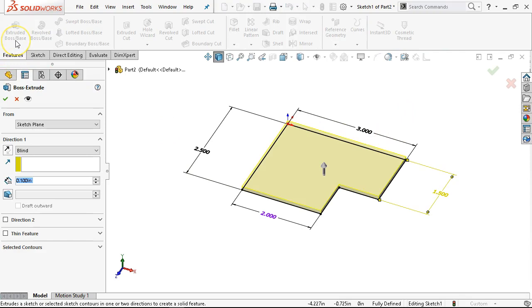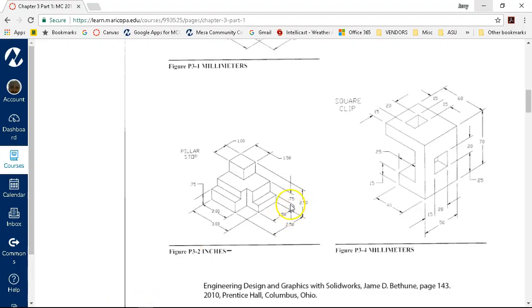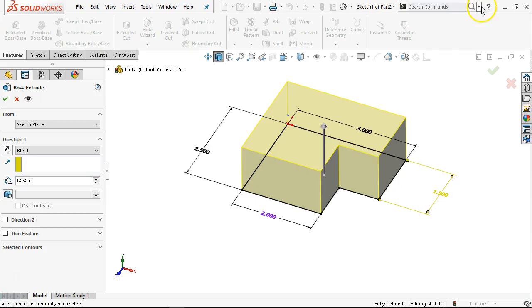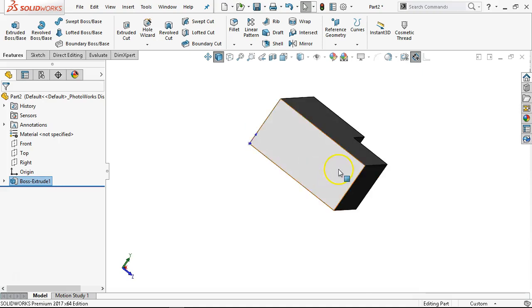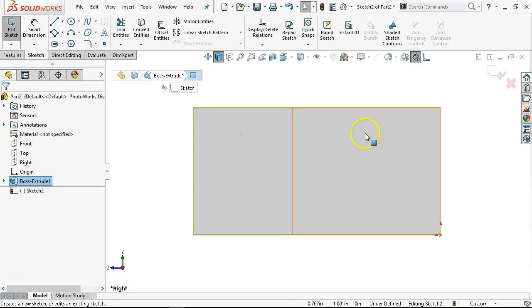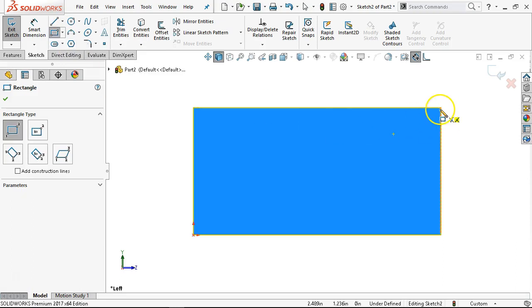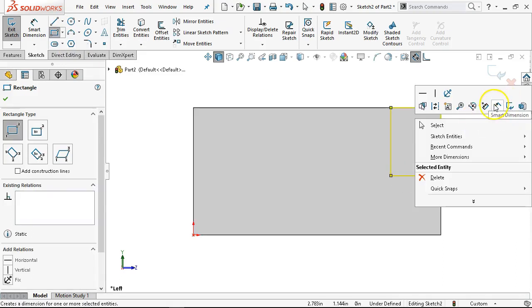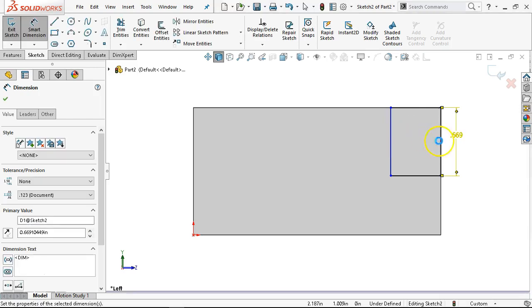We're going to extrude, and this is going to a height of 0.75. Nope, 1.25. Okay, and that's going to be the 0.5 plus the 0.75 to the top of that first level. Direction-wise, let's go with one of the corners, and we'll go to a Control 3, and this can be just a corner rectangle. And that one was, so not a good choice.